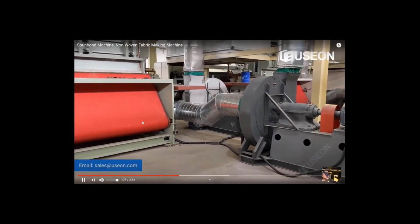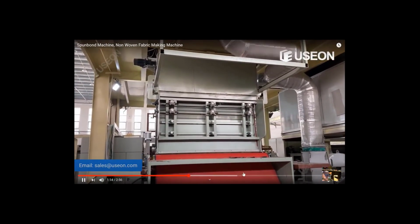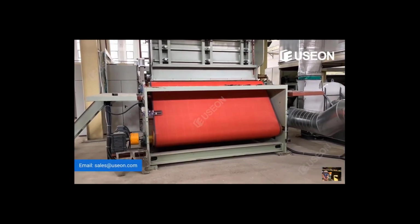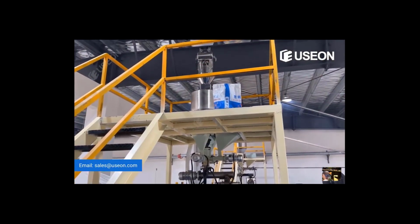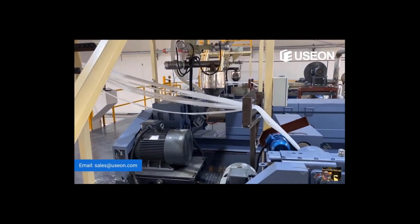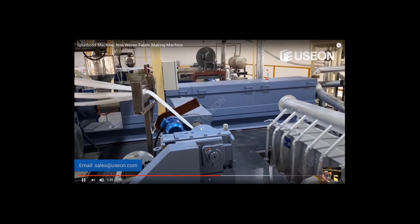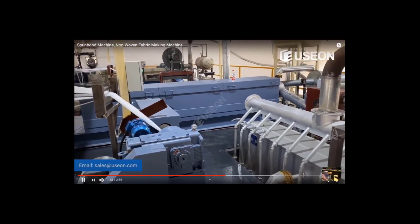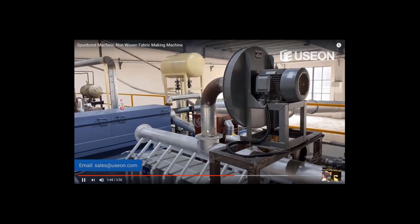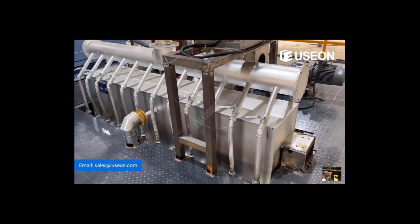Oh, this is great. See, here's that salmon colored belt, and what they're going to do is melt a bunch of polypropylene and spin it into tiny little fibers and then blow air onto it as it hits that belt. And that's what makes the white product that you're seeing. I don't know what's going on here. Maybe they've divided the streams into several streams. I don't know. Maybe they're recycling. Anything they cut off, they will recycle and put back in. If you have to trim some of the material, they will capture that and melt it again. You could do that multiple times without a problem.